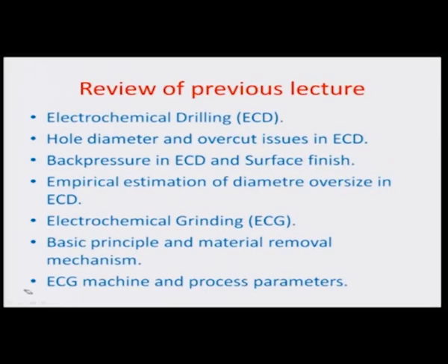We talked about various electrochemical machining processes like electrochemical drilling, where there was a concentric discharge of the electrolyte from the center of the tool. Then we talked about various associated problems related to hole diameter and overcut size in the ECD process, as it is commonly known. We also discussed in detail the back pressure issues in ECD and the associated surface finish.